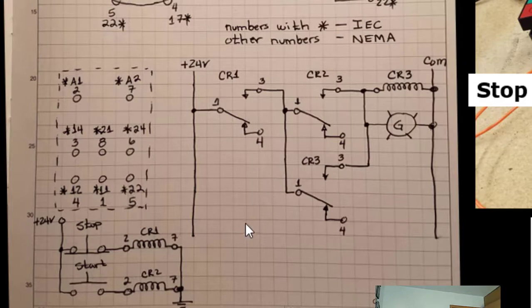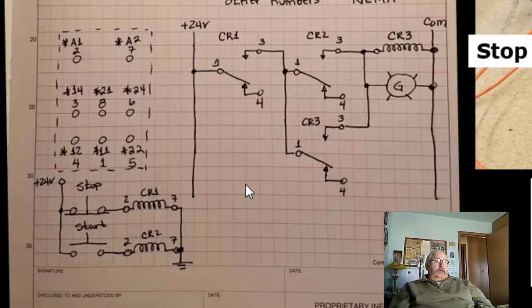What I did then was I drew the schematic using electromechanical relays. And there's other ways to draw relay contacts. And if you saw my previous video for the I/O interaction, you'll see that I used a different symbol. You should get used to seeing both of those symbols. But the very first thing I did was I used my physical field devices, my stop push button, my start push button, and that's what's going to control relay coils.